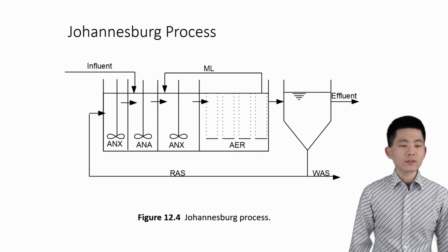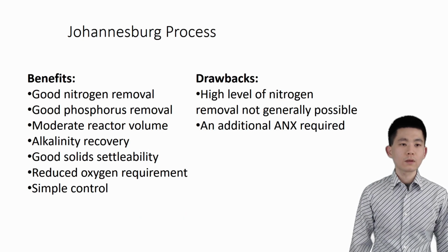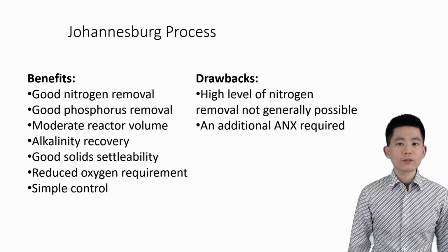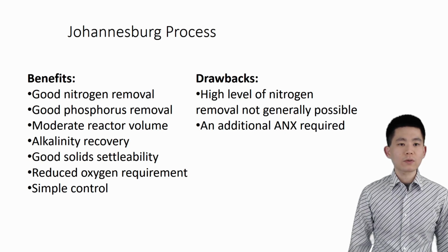The influent that contains organics, however, is fed directly to the anaerobic zone to support the growth of the PAOs. This is another process that focuses on phosphorus removal and allows some nitrate present in the effluent. The additional anoxic zone replaced one recirculation line, so less energy is needed for recirculation, but more construction cost is needed.